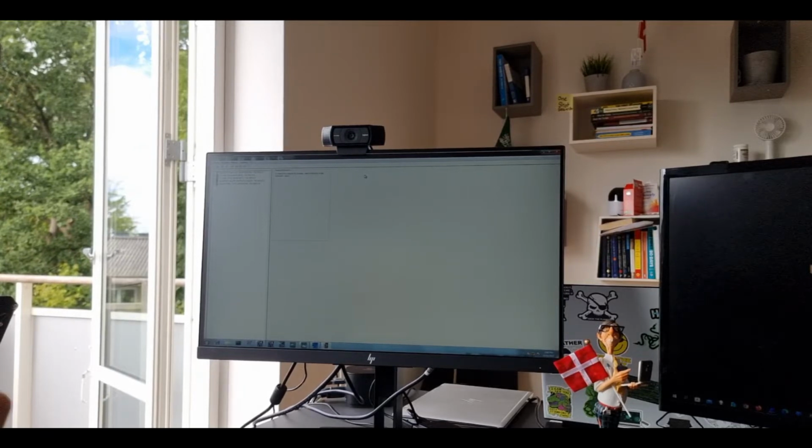Or we are adding a spare part, let's assume a network switch or a new PLC, and we need to configure the IP address for that PLC. Then we use this kind of scanning tool. As I said, it could be from the vendor or it could be an open source tool. From a functionality perspective, it's really important. We really need such a tool because it makes our life easy.